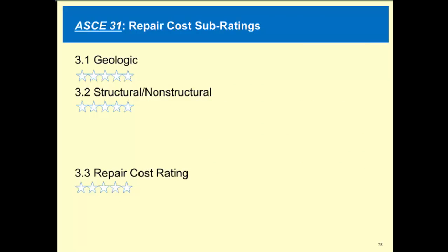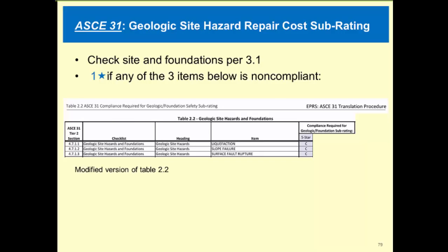So for the repair cost, there are 2 sub-ratings, unlike in the safety rating where we had 3. We're combining the structural and non-structural. We'll jump into the geologic site hazard sub-rating. You would go into Appendix C, Section 3.1. It's a little bit simpler. If any of the items below from Table 2.2 are non-compliant, then your sub-rating is a 1-star. If you have compliant for those 3 items, then it's a 5-star.